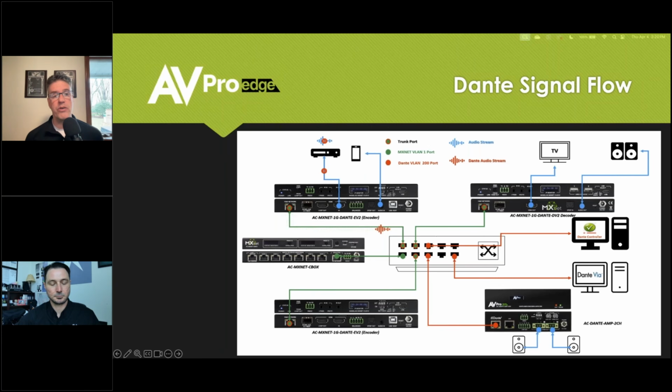But I'll tell you what, with a bring your own device situation like that, point to point, I would set the EDID for whatever your display is to make it a little easier because you don't know what kind of computer is going to come in that room or what someone's going to try to force in there, and you don't want them not getting a picture at all. So particularly in a point-to-point, I would actually set it for what the display is. The other thing to think about too is the computer itself might not scale very well. So the signal scaled out of the computer might not look very good on a big TV or big projector.